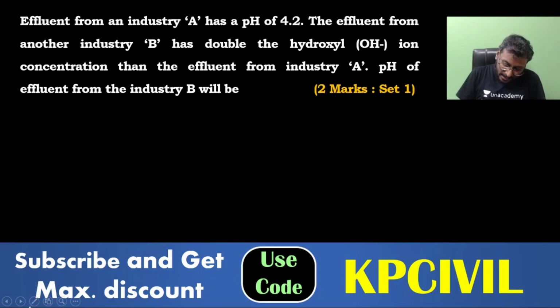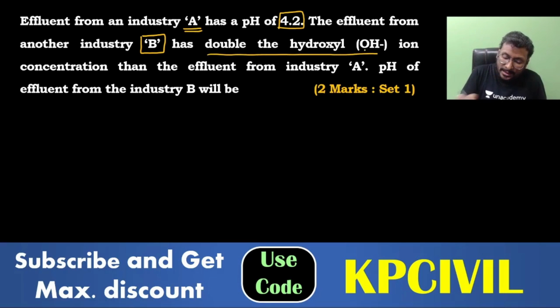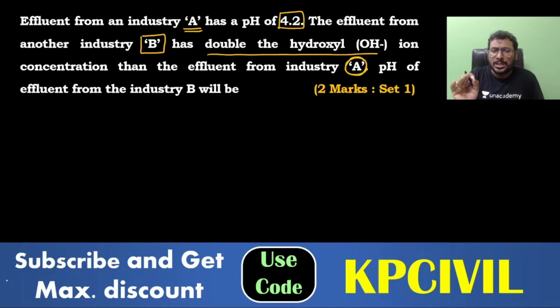Effluent from industry A has a pH of 4.2. Effluent from another industry B has double the hydroxyl concentration of A. The pH of effluent from industry B will be a simple question, the most simple question.